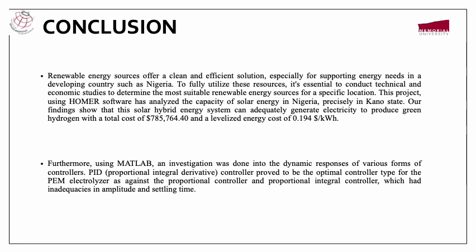$0.194 per kilowatt hour. Also, from our MATLAB analysis, we see that there are various forms of controllers, but the PID, which is the proportional integral derivative controller, proved to be the optimal controller for our PEM electrolyzer as against the other forms of controllers.